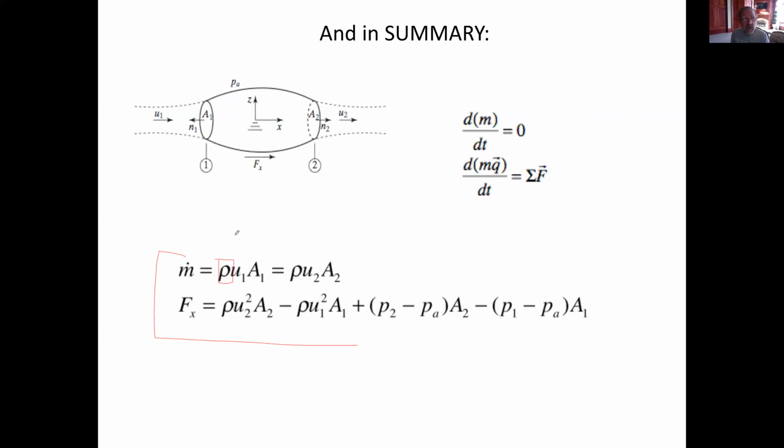Density variation in the flow is a result of, say, the flow going around this object, and because the velocity is changing, the density will change. We're going to see that for velocities which are subsonic, the density changes are very small. So for the liquid, remember, we went down 1 kilometer in the ocean and it compressed less than 0.5%. So the changes with rho for liquids are very negligible.